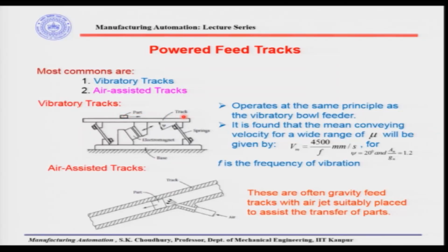So, because of the combination of these two, the parts will be moving on the track, and it will hop and then move forward, as in the case of the vibratory bowl feeder. It operates on the same principles as the vibratory bowl feeder.